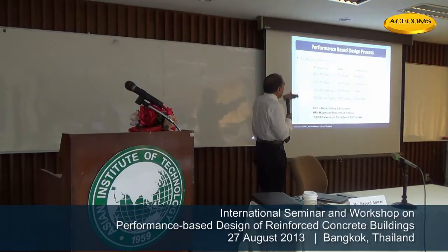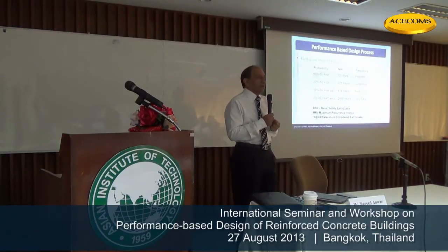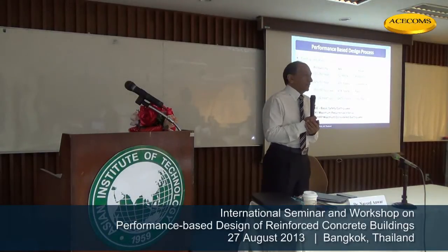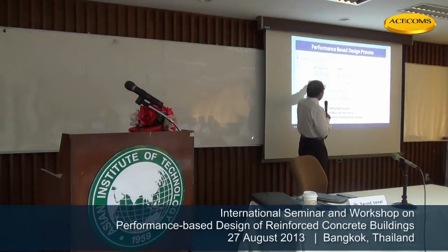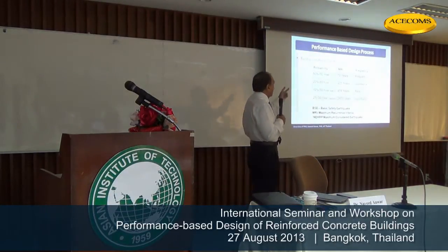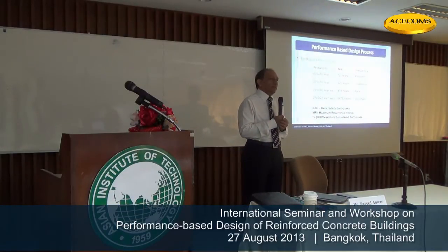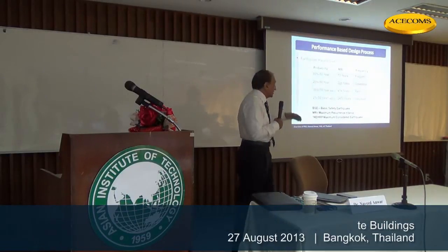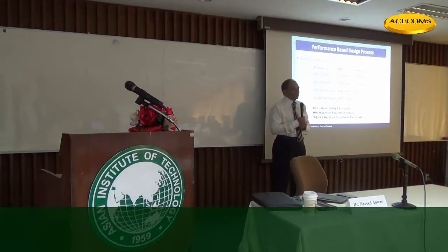And that can be defined in these categories. We can estimate the hazard level in these categories. We assume that the life of the structure is about 50 years, let's say. In that 50 years, we can say an earthquake 50-50, 20-50, 10-50, 2-50. That means a 50% chance of that occurring, 20% chance of that occurring in 50 years, 10% chance of that occurring in 50 years, and 2% chance. So these tell us frequent, occasional, rare, very rare earthquakes.